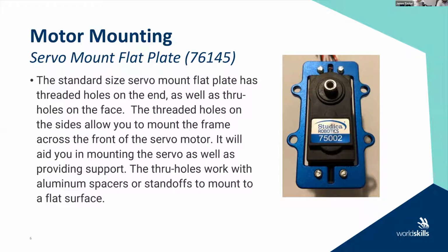All right. When you go to mount the motors for this, you're going to use two different types of motor mounts in the design, so I thought I would talk about that. You will use the servo mount front plate that I'll talk about in a second. The standard size servo mount plate has threaded holes on the end. There are 4 threaded holes on the end, and it has through holes on the face.